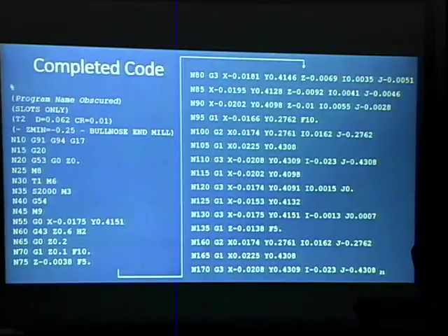So this is simple by the standards of G code. The first part, everything up through, I'd say, about N55, is really a preamble. It's saying, turn the machine on, what coordinate system, what axis system am I working in, what unit system, am I working in inches or millimeters? Then we get into, like, line N75.